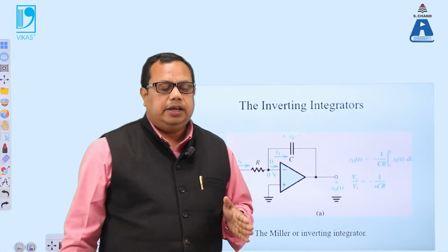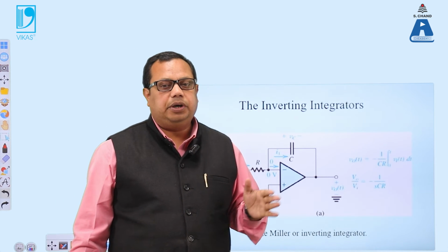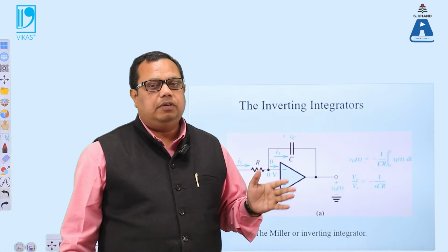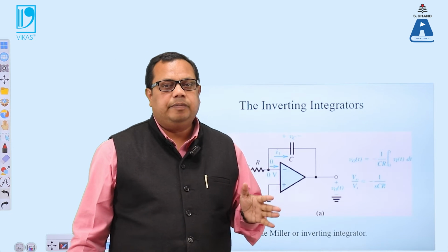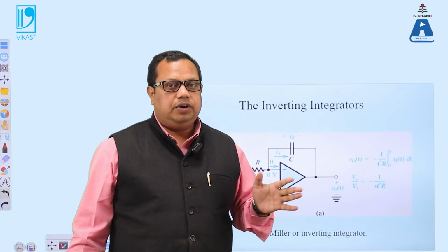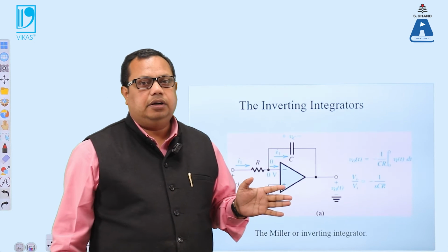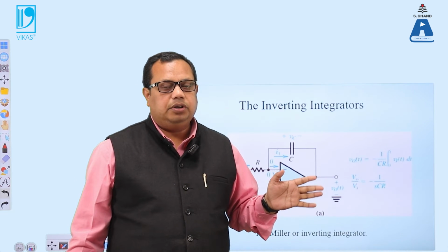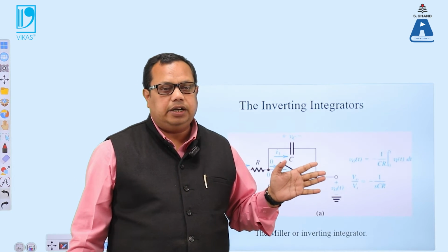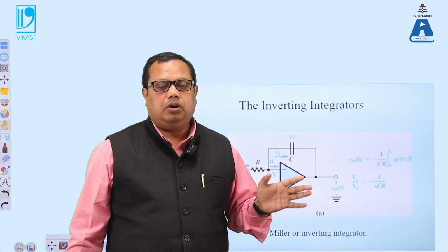Because we can see that in the adder, the differentiator and the integrator, the position of the particular resistor and the position of the particular capacitor are different. We use them differently in the integrator and differently in the differentiator. So both the connectivities are different, because in one case we need a total effect, and in another case we calculate the output according to whatever changes occur.